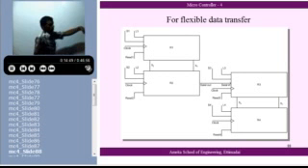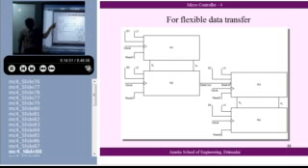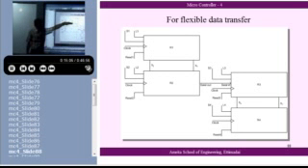I take the first register, I can give serial data. I load. After loading the full 8 bits, I can transfer to this. For that, I do parallel output here by enabling read. I do parallel loading here. 8 bits I load in parallel. So this data which is serially input here, I take as parallel output and load here.